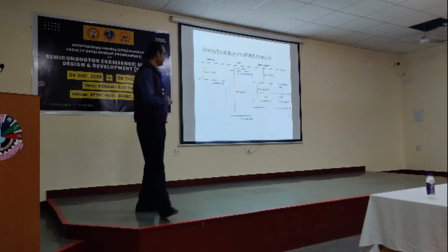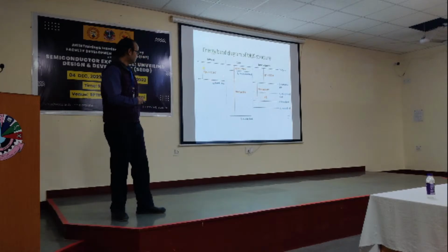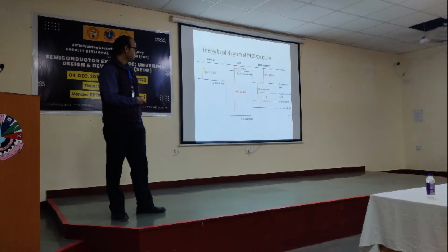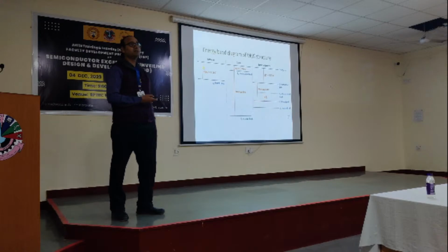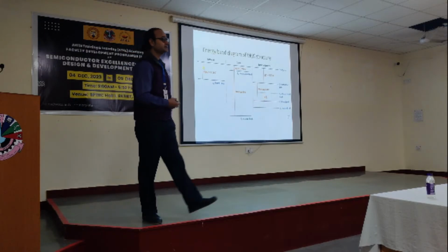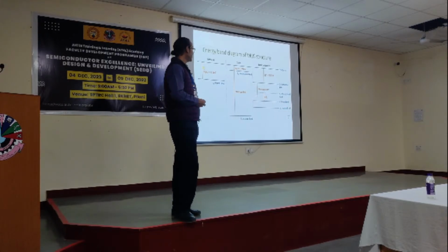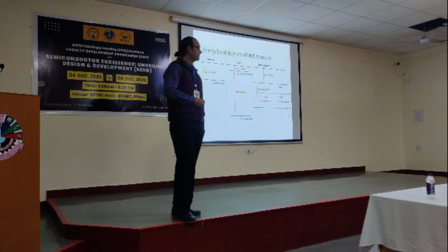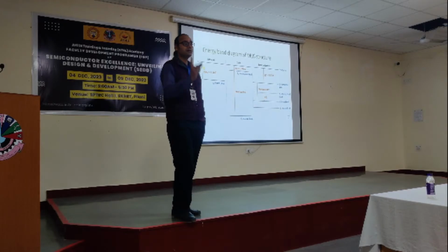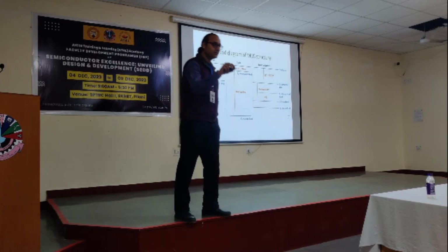So these electrons will deplete holes in the p-type substrate, and at the surface we will have depletion. Depletion of holes means, where will the band bend? This valence band will get away from the Fermi level. Why? Because we are depleting holes at the surface.